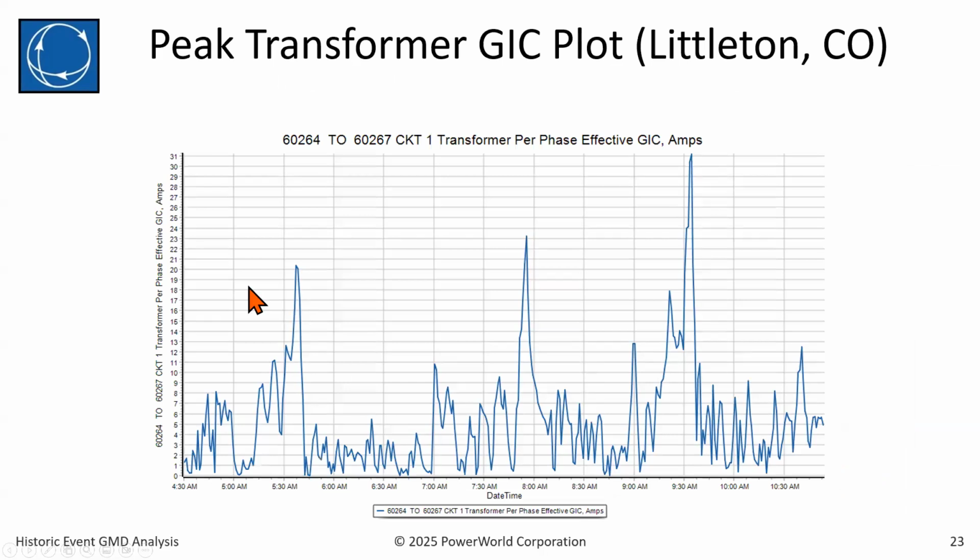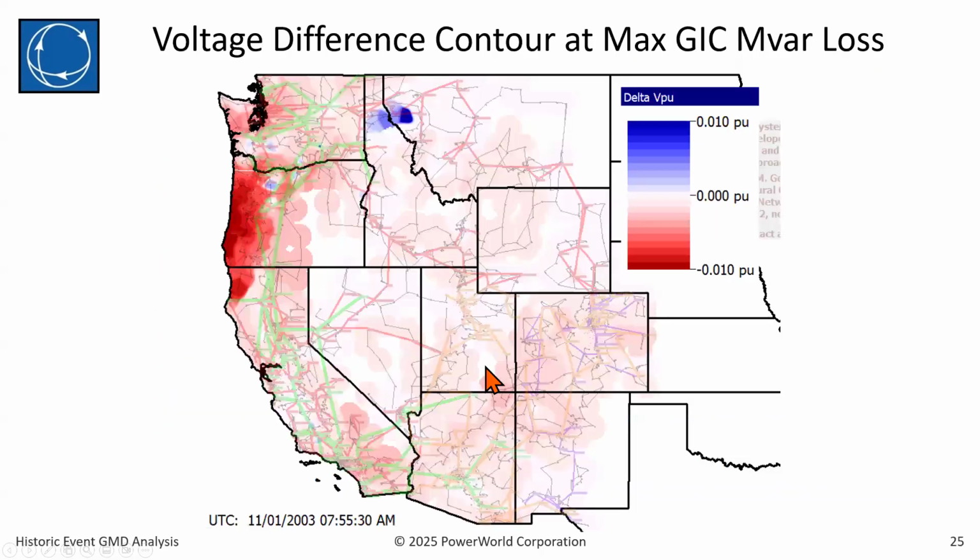So there are different ways that you can look at it, but the transient stability tool is great for quickly processing the data just based on the GIC calculation. The Timestep tool can be useful for doing nonlinear power flow solutions. And if it's an event like nuclear EMP, where the dynamics are faster and fall into the transient stability realm, you can then use the transient stability tool to actually do the dynamic simulation as well. Anyway, this is the trace that I showed, after solving that time point in the Timestep simulation.